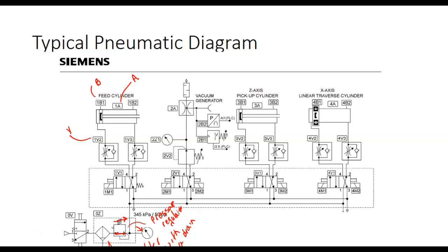We usually run ours around 40, 60 or 50 psi. I think that the Festo, they recommended we run 50. The Amatro runs 60. We get around 200 psi out of our big compressor over there. So that regulator is regulating it down. What do you have to do? Pull the cap up, turn it where you want to, snap it back down. And that way somebody can't accidentally do what? Turn it.